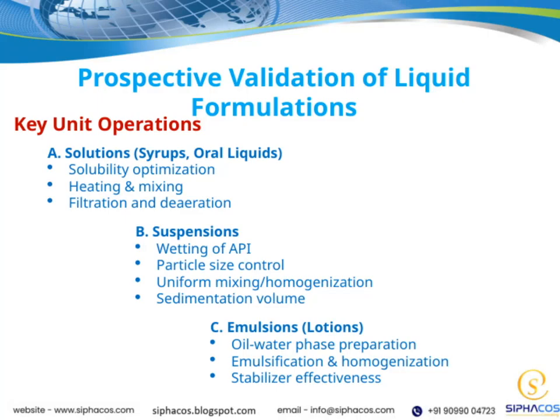Let's take a closer look at some key unit operations involved in liquid formulation development. First, for emulsions like lotions, the process begins with oil-water phase preparation. This step is crucial because it sets the foundation for a stable emulsion. Next is emulsification and homogenization, where we ensure the oil and water phases are thoroughly combined to create a uniform, stable product. The effectiveness of stabilizers also plays a vital role here, helping to prevent separation over time.